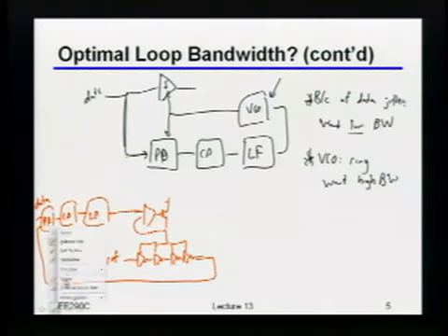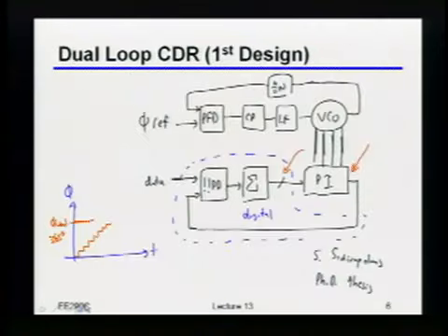So this is like your data, and that's some reference right here, okay? Well, how do you wrap this around, right? The only way you could wrap it around would be to suddenly jump this control voltage from wherever it used to be to some magic point that you now know has wrapped, right? So that's why it's actually pretty tricky to do if you really have an analog loop like this, okay? Whereas if you build the DLL out of the phase interpolator, where really all you're doing is selecting which phases to blend between and how much you blend between them, well, now actually, no problem. You just wrap around and you get exactly the right phase that you wanted, okay? Pretty easy to achieve monotonicity with this sort of phase interpolator.